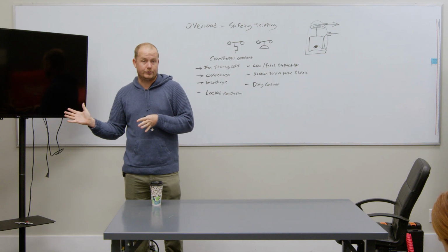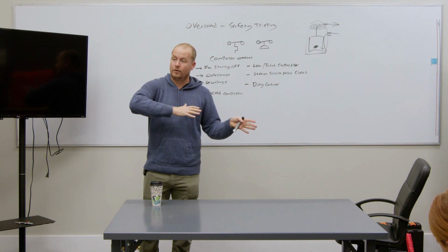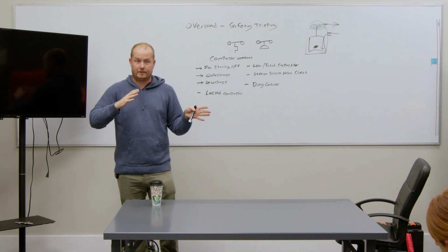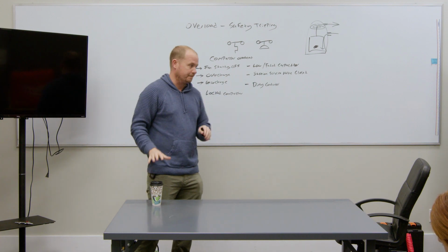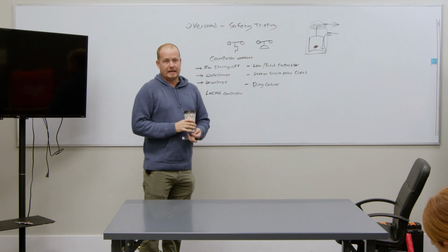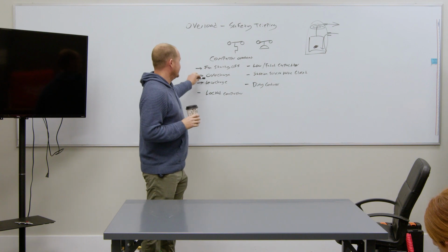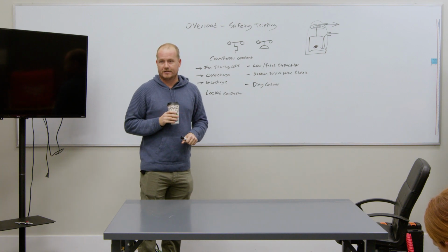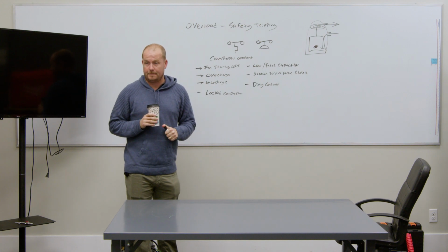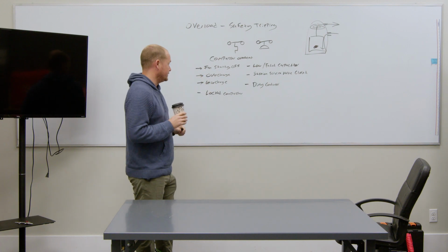Too high because it has to do too much work. Too low because that causes it to overheat eventually because it's not cooling it well enough. Does that make sense? Everybody follow that? Okay. Now again, you have to get to the extreme side of these before it happens. It's not like a tiny bit of undercharge is going to cause the compressor to overheat. It's not like a tiny bit of overcharge is going to cause that to happen. They tend to be on the further edges of that.